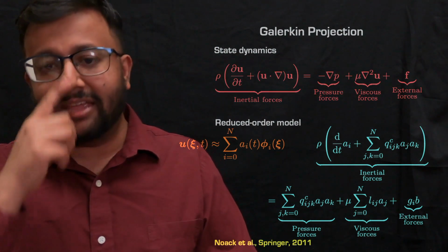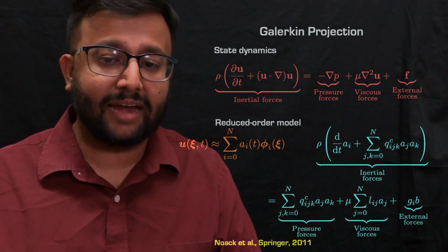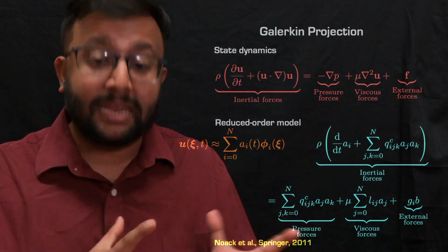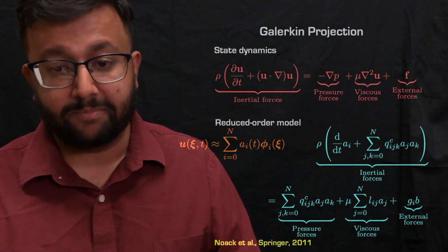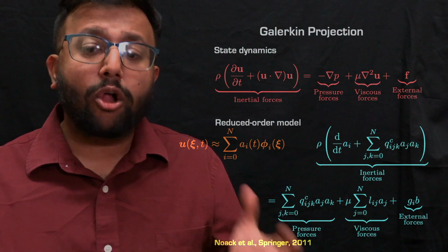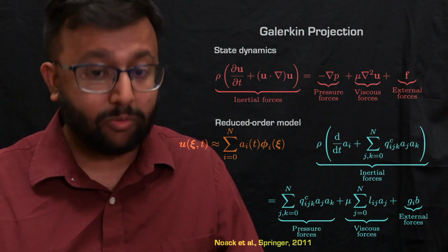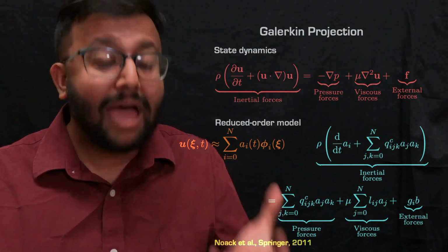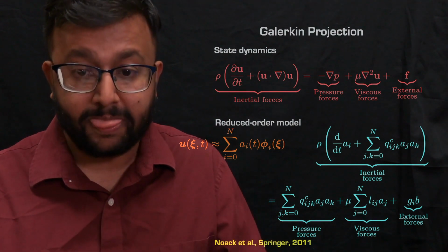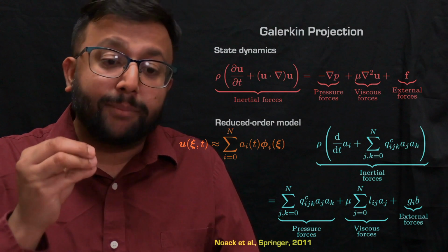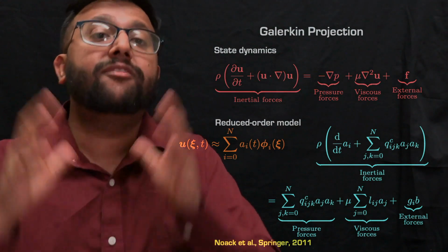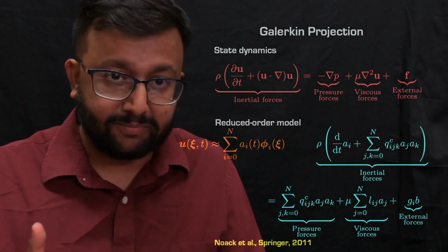If you recall in the last lecture, I mentioned that we need to subtract the mean before we perform POD. So we can also think about the i equal to 0 mode here being the time averaged flow, or the mean flow, and the associated temporal coefficient being forced to be unity, or 1.